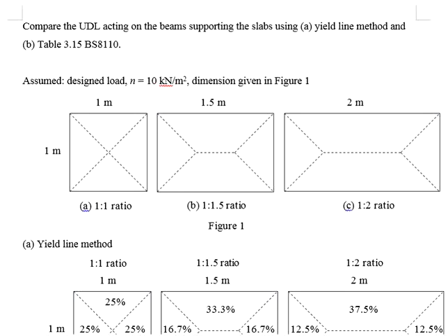Hi, let us talk about the analysis of reinforced concrete beam. You know that in the reinforced concrete structure, the beams are used to support the slab, whereas the slab is used to withstand the loads, which are the permanent actions and the variable actions. The permanent actions and the variable actions normally appear in kilonewton per meter square. You can get those from Eurocode 1.